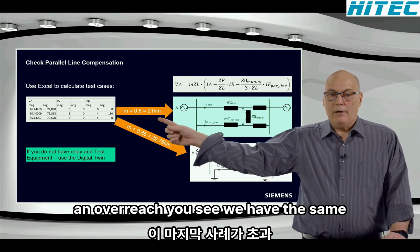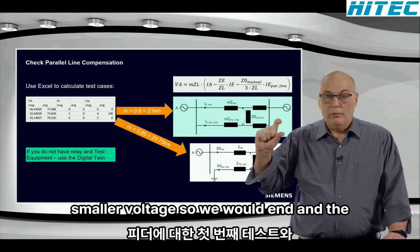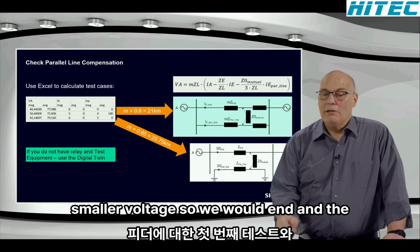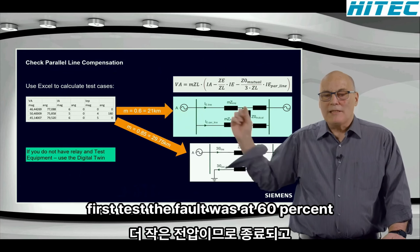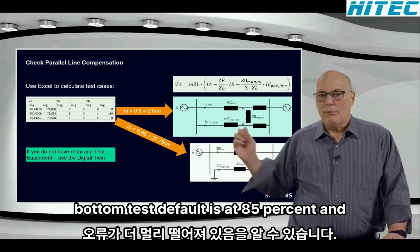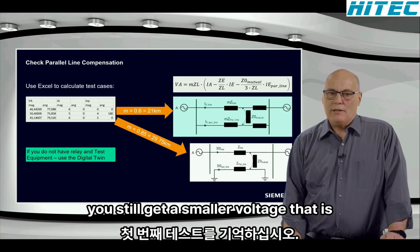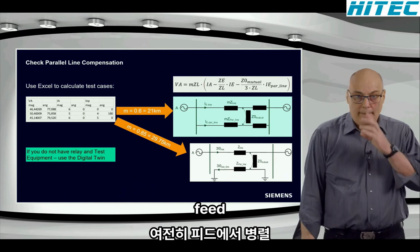You see, we have the same current in the third test as in the first test on the protected feeder, but a smaller voltage, and the fault is further away. Remember, for the first test, the fault was at 60% and gave you 46 volts, and for the bottom test, the fault is at 85%, and you still get a smaller voltage. That is the significance of the parallel line infeed.